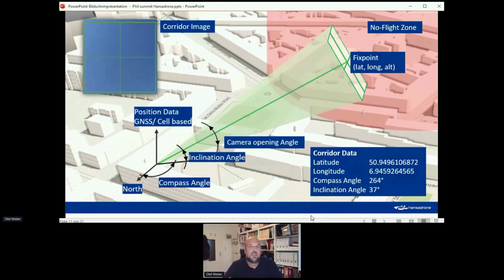So this is the way actually for the drone to fly from cruising altitude towards the customer. And the drone would now fly to a fixed point in the sky, which is like the intersection of that approach corridor with the cruising altitude, and it would start its approach flight from that fixed point.